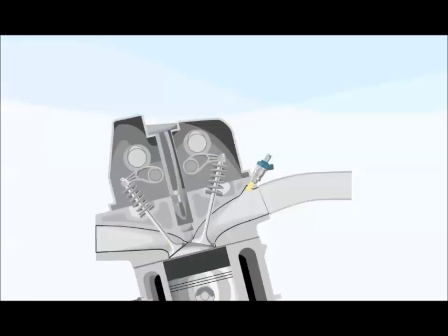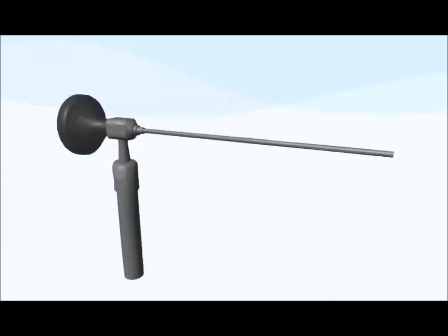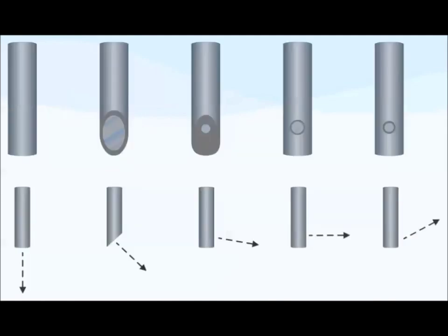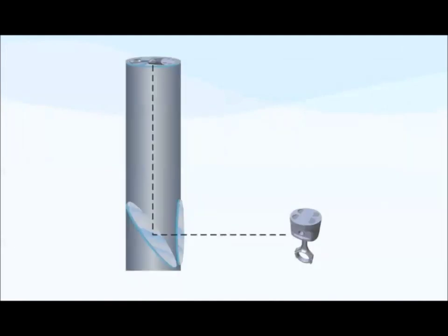To use this tool, technicians insert the borescope tip through the spark plug hole or injector port. Therefore, the borescope shaft must fit through these openings. To see to the side, rigid borescopes use angled tips. Using these tips allows you to see images to the side of the borescope shaft.